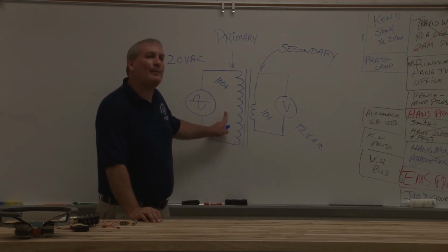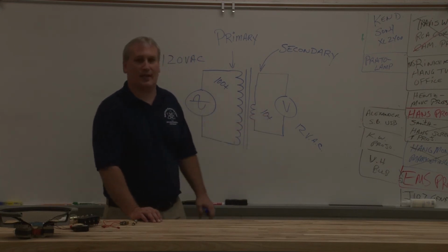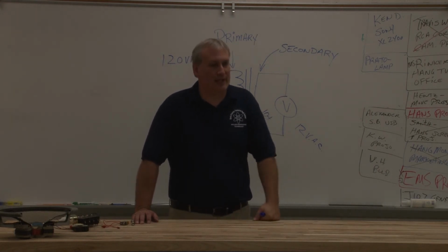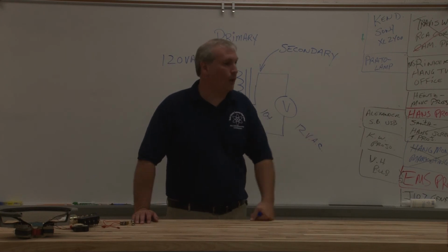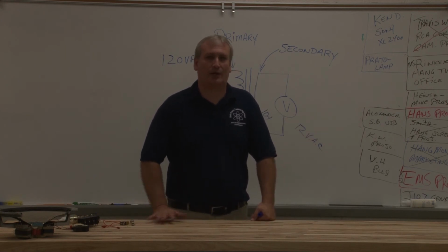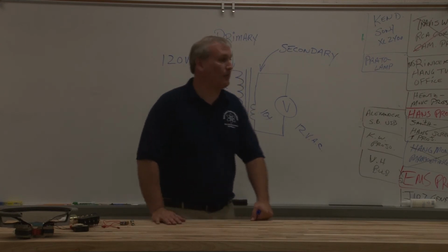What if I did the opposite? What if I put less turns on the primary and more turns on the secondary? Dakota, say that louder, please. It raises the voltage. Very good. It steps up our voltage. Transformers step up or step down. So raise and lower is correct, but let's use the terminology that we're going to stick with in electronics. Transformers will step up or step down. So in this case, it steps up the voltage.